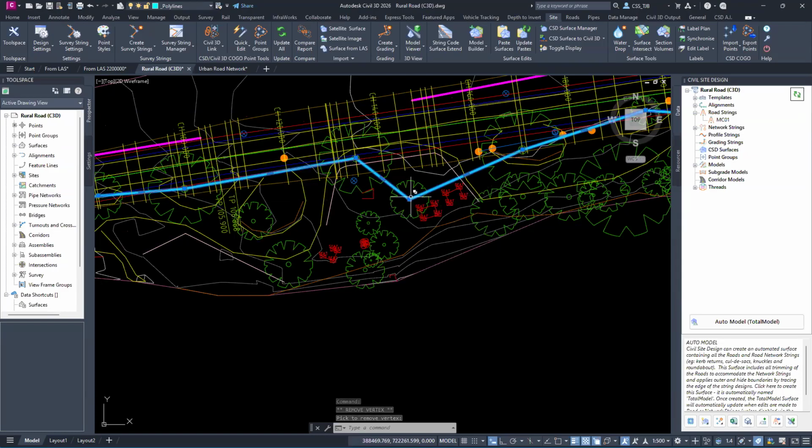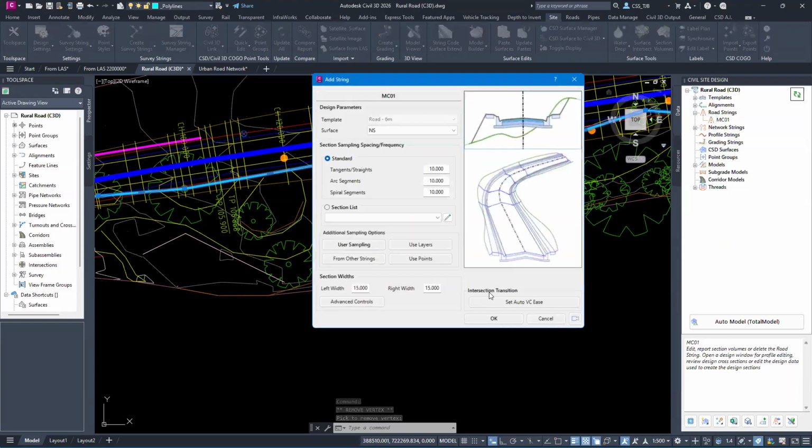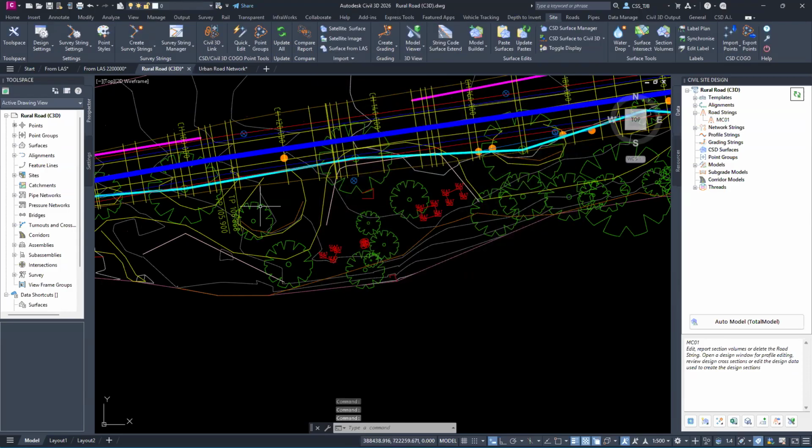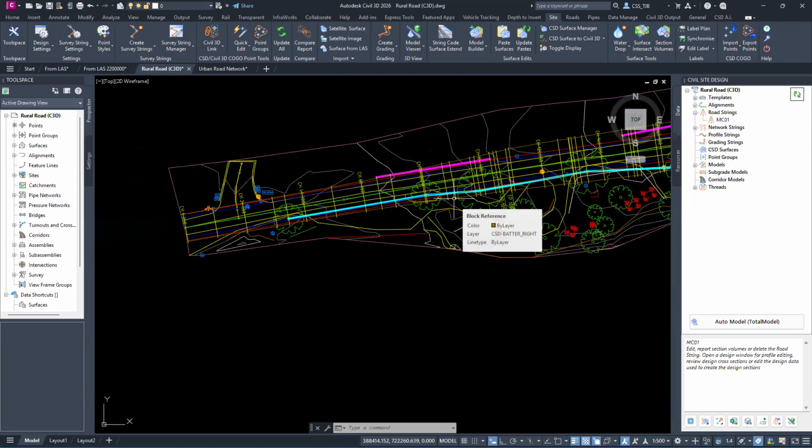Oops, go a little slower. And then I resample the job. You can see those two sample points that lined up with those two trees disappear. So anytime you make a change to the source objects within the search distance, hit the resample and they all update. So actually quite a useful tool for sampling things graphically as opposed to numerically.